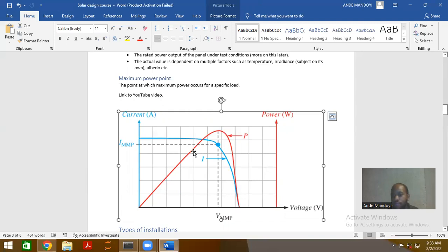And that's where MPPT comes from, because it'll adjust the voltage by changing the duty cycle in the buck converter, or boost converter, doesn't matter. It'll adjust the voltage such that you're always at this optimum power point or very close to it.